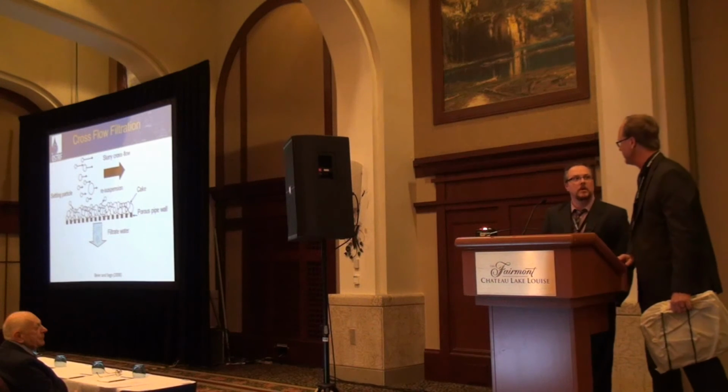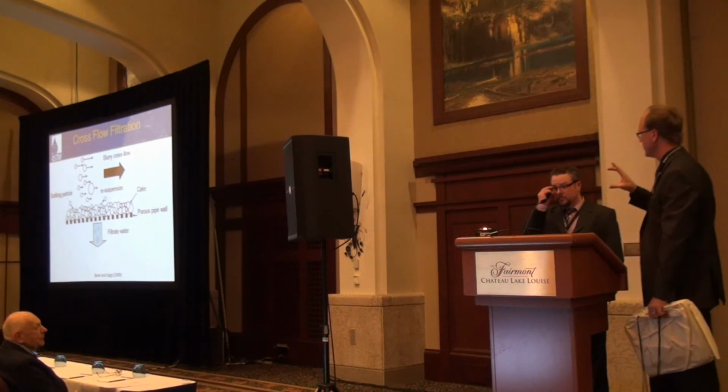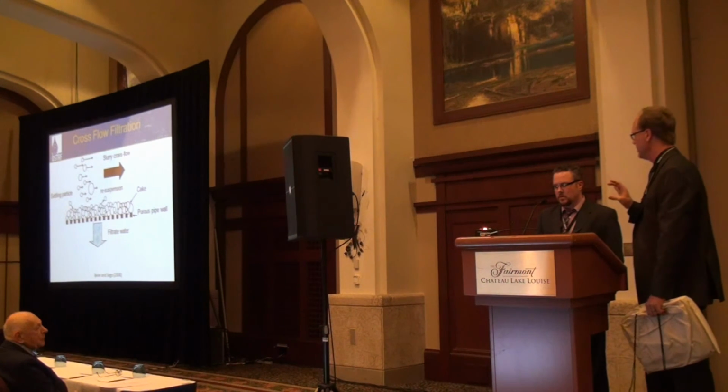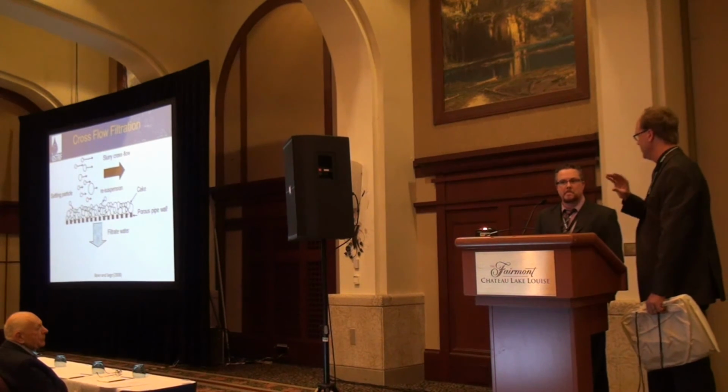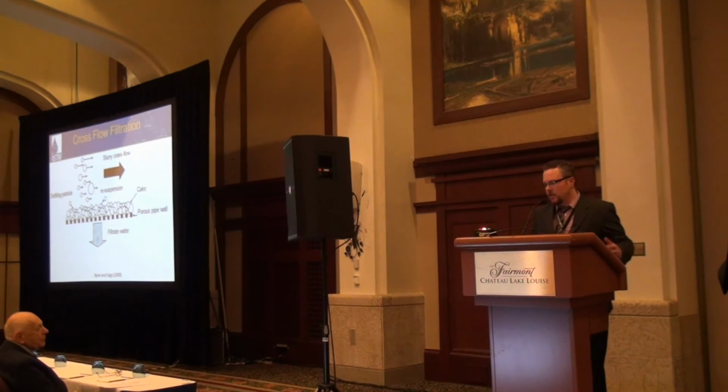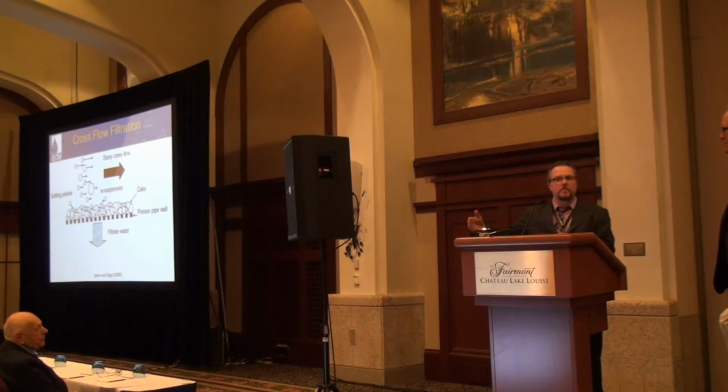I have a question actually for you. On this pipe, when you actually get the slurry being deposited, was that a fairly constant solids content, or would it vary with time? Or did you know what it was ahead of time, or how did you account for that? Because then you'd have to adjust your compression curve up and down to account for your initial solids content at the end of this pipe, right? So I think in the design, you'd have density meters, and towards the end of your system you could have kickoffs. So once your tailings got to a certain density, you could discharge them a little bit earlier, or have them stay in a little bit longer so that you could maintain that final density at your target density. Okay.